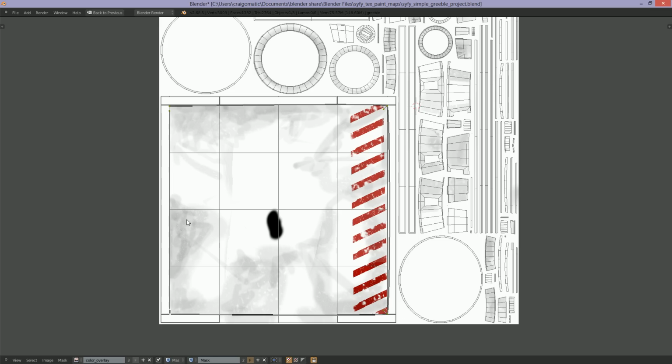Now I have to select the first and last and Alt-C to close. I'm going to select all of the verts, hit V to bring up the vector alignment, and change it to vector so it turns into a square. And I'm going to change that mask name down here to control underscore shadow. I want to try and make use of a shadow filter on it.